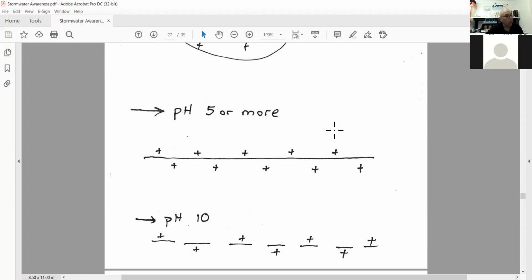Does chitosan work with truck wheel washes? I've had this question come across in a couple ways, and in many cases, yes. However, there are pH limits. So for truck wheel washes from a concrete plant, where elevated pH would be expected, chitosan's not a good choice. When used on muddy sites where track-out pH is 5 to 8.5, expect very good reaction from the chitosan.